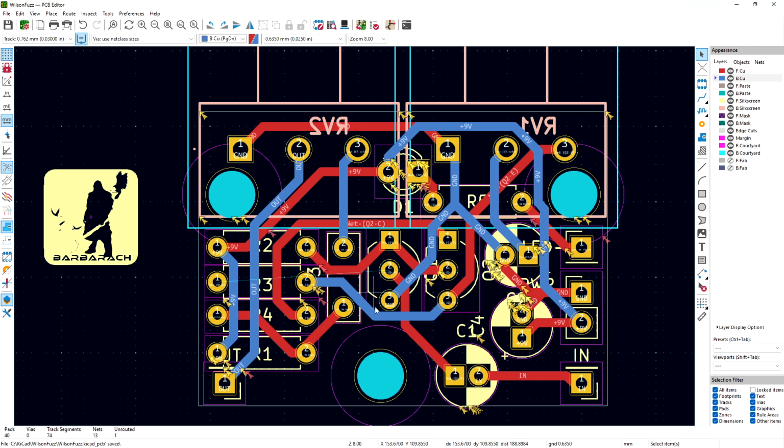If you wanted to do this, you could play around with this a bit more. You could try to change the wiring. We can do vias, or I don't know how you say that. But let's see what we can do with this. I could get it on top copper here, and then make this line smaller here.